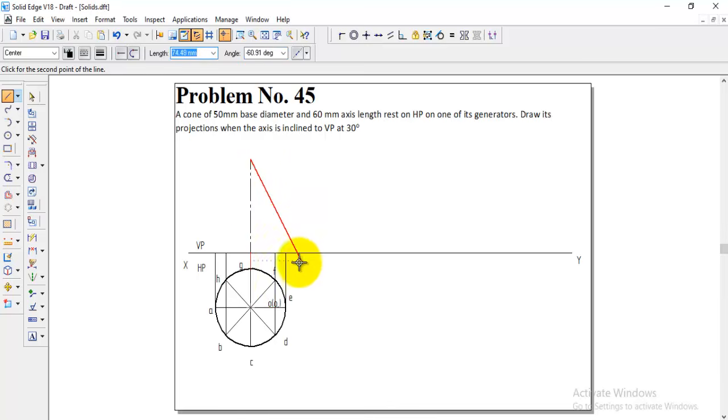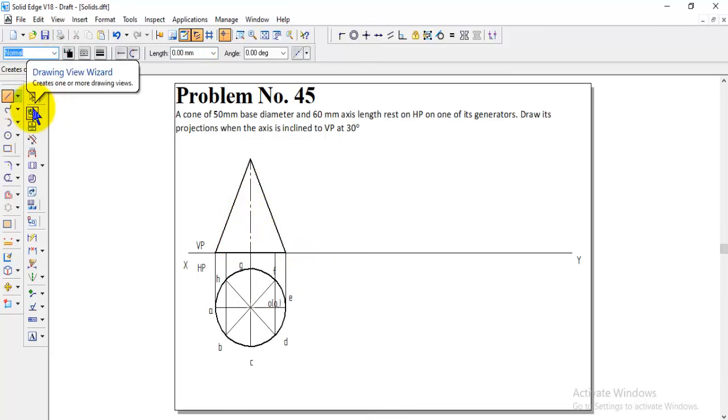And after that, we know that in the circle only the periphery can be seen, so we draw only the borders with a visible line. Go to line, visible line, and draw only the outermost portion of the cone as visible. The inside edges will not be visible, so those we draw with normal lines, like from here. This central line we already drew here, and this one.